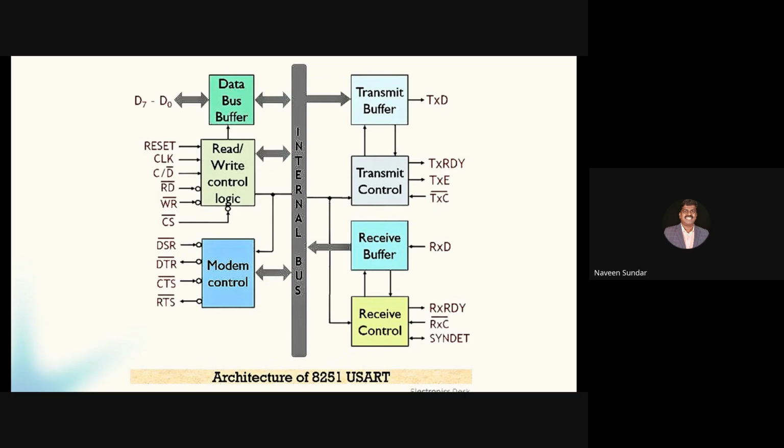Then we have TxRDY, that is transmit ready, which indicates the buffer is ready for new data, so the CPU can send the next byte.